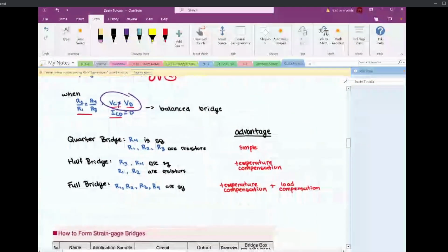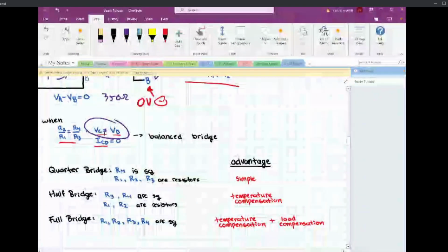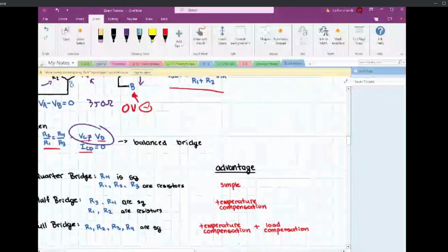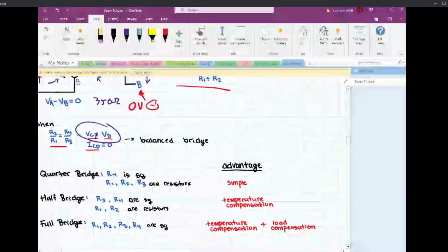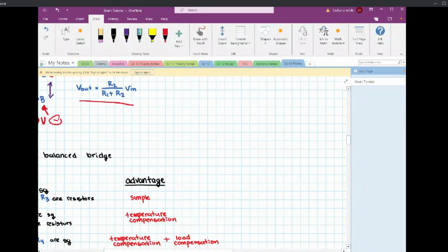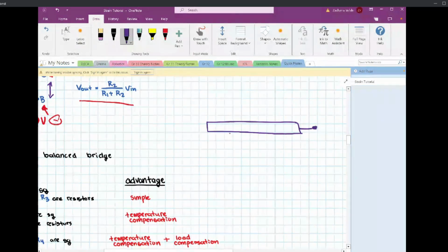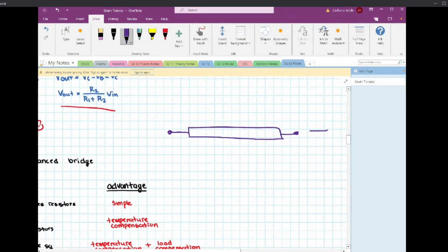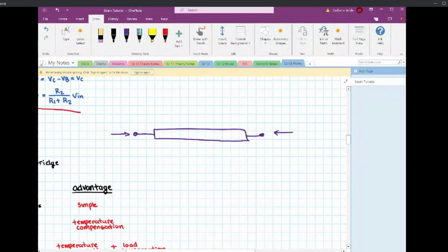And it's the same thing for a full bridge. Another important thing we want to do, which is why we mostly make full bridges these days, is to compensate for different kinds of loading. Say you have your beam, pinned on two sides, and you only want to measure forces going axially inwards, like the tie rod on a car.